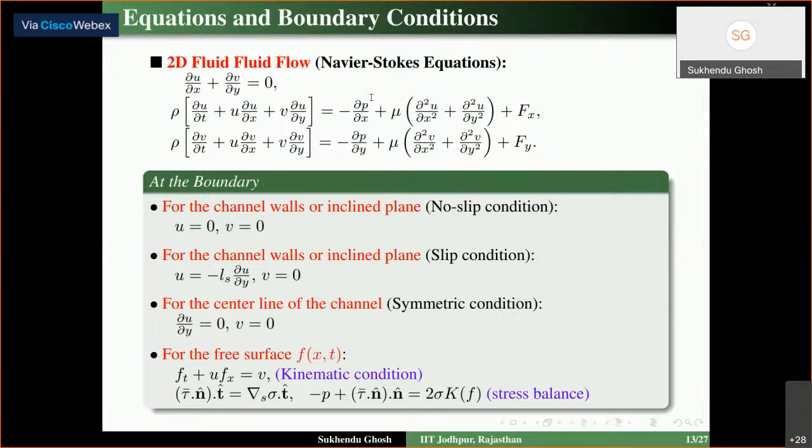That means this P represents the pressure inside the system. So the total pressure with respect to x is not changing, and therefore this is 0. Now from all the other terms, what will we get? Only the non-zero term, that is del square u by del y square, because u is only dependent on y. So del square u by del y square equals 0 will be the modified equation for the equilibrium solution.